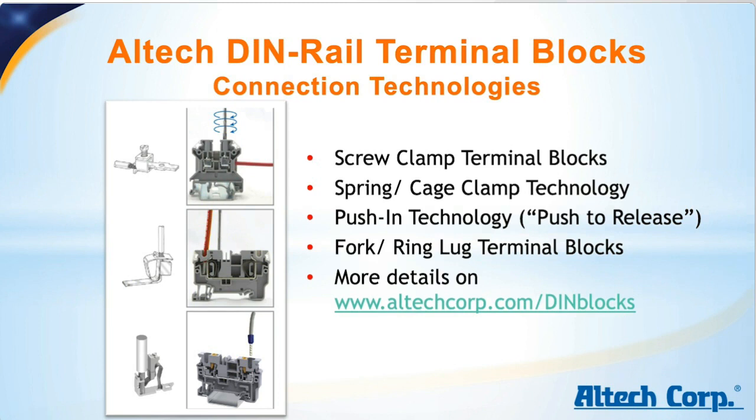Now the spring or cage clamp technology. Here we have a preloaded spring, and by inserting a screwdriver into a slot, we open that preloaded spring. That screwdriver pushes the spring away. Then we insert our wire into the clamping space. You remove the screwdriver, and the conductor automatically makes contact with the terminal. This way we have a connection in just a few seconds.